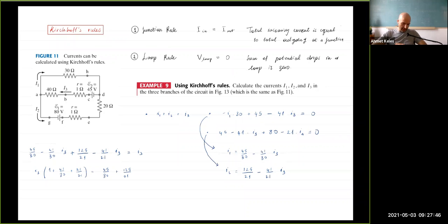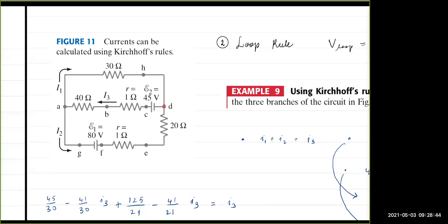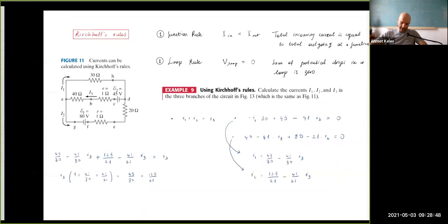So the plus is like this, okay. There are two things, right? The resistor and the battery. And in the resistor, if you are going in the same direction as the current, because my loop is independent of current, right? I could follow my loop like this or like this. But I chose my loop to be like this. So my current and the loop are in the same direction. If this is the case, whenever I pass through a resistor, I put a minus, because when you pass through a resistor along the current, voltage here should be higher than voltage here. So this minus this is a minus, so you have a minus. And whenever you pass through a battery, you look at the terminals, right? From here to here, you go from lower to higher. So higher minus lower is plus, right? That's a good question. Is that clear?